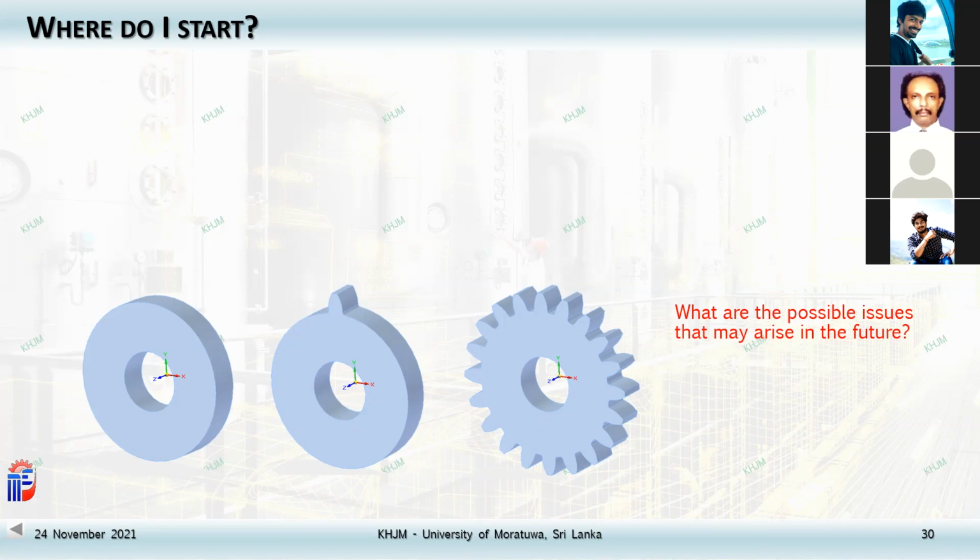No idea. So if you can think of the future possible changes, then you will make your model flexible, or else you will not model until the final stage. So you know that I'm going to modify this one anyway after that. Adding all these, I said earlier, the minor features. Remember, there are no minor features as such in synchronous modeling. It's only in the ordered modeling because there is an order. Major should come first and then the minor should come next.